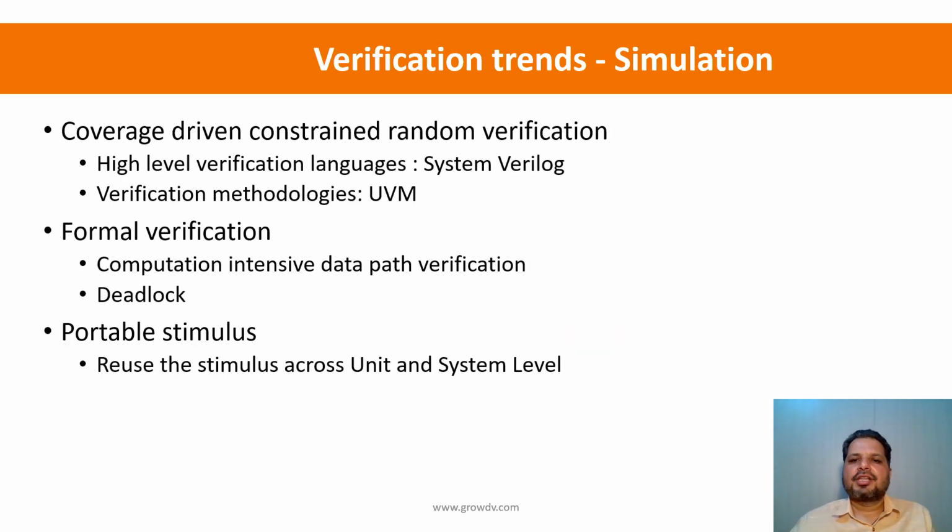In terms of verification trends, there are different technologies now available that can be utilized for performing the verification, and we are going to predominantly focus on coverage driven constraint random verification. It's also called dynamic simulation based verification. And here, as a part of the industry, as we have seen in the trends as well, the high level verification language that we use is SystemVerilog, and for SystemVerilog the reference is the IEEE's LRM. That's the main reference. I think everyone should definitely get that. We will look into more details as we go in the further sessions.